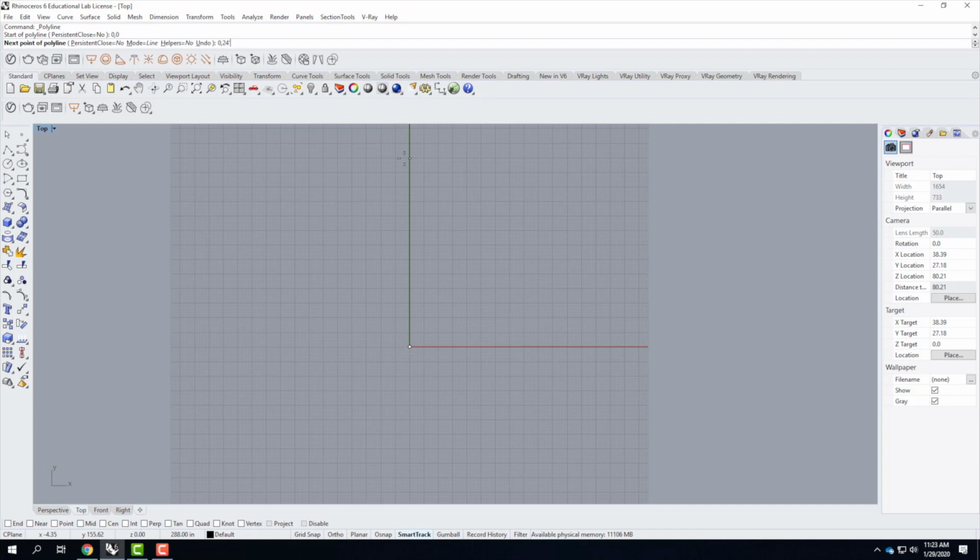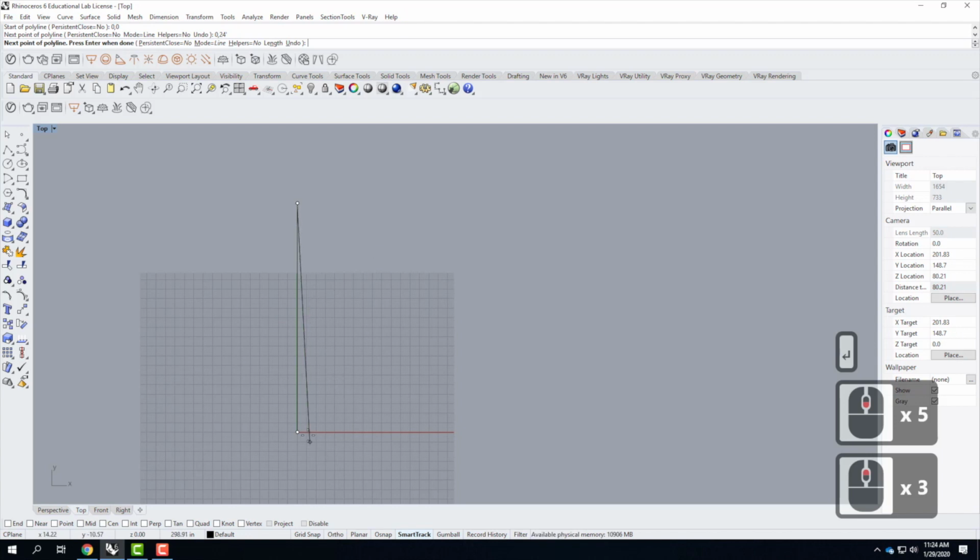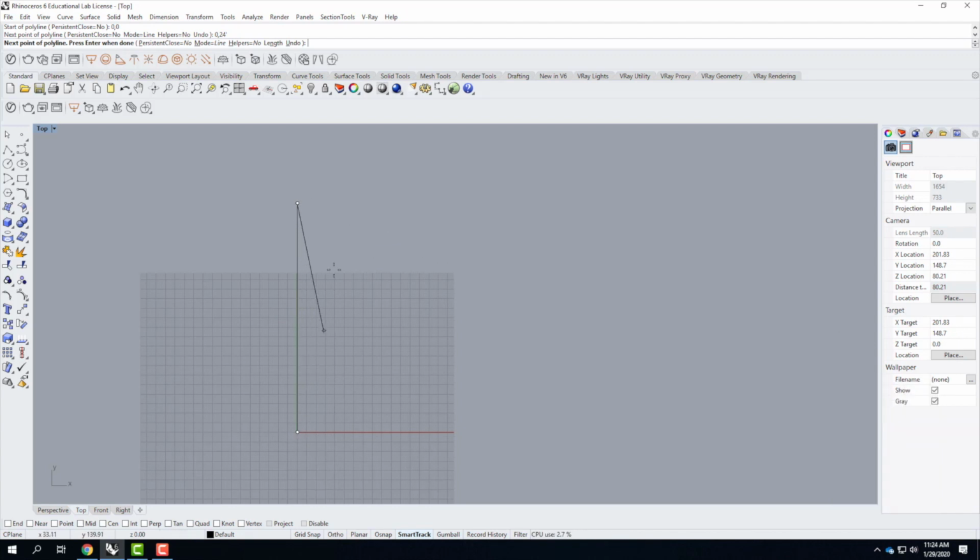Though if you leave the inch mark off, it will assume inches. So you don't always have to put the quotation mark on. So when I type 0, 24 feet and press enter on the keyboard, I have to zoom out a little bit to see it, I get a line that is exactly 24 feet long going up in the y direction.